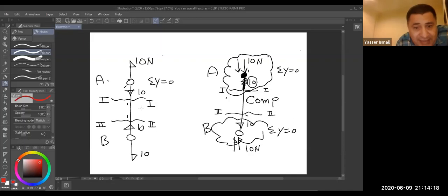This force is 10, tension positive. Why? Put your finger here. Is this force pulling or pressing? Pulling. That means what? How you are going to define negative and positive internal forces? By this technique. Very simple technique, very easy, and you can easily, let us see what.